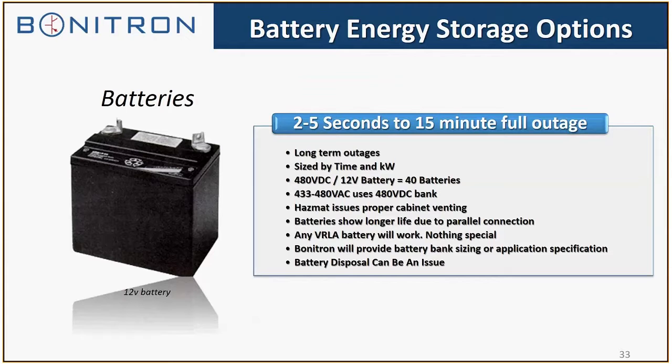My experience has been 2 to 3 years. When I walk into a plant and they've been using a UPS or some sort of battery type backup, they tell me they've been changing them out a lot quicker than what the battery vendors say. If you do have a customer that wants to use their own batteries or their own energy storage, we can provide battery bank specs.